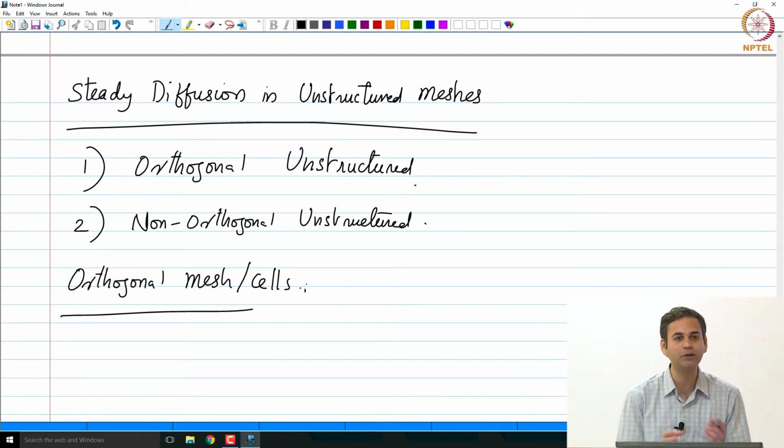So this was not happening because we have an area vector of the face in the same direction as the gradient, right? So the gradient direction is partial phi partial x, right? That is connecting what? That is connecting the cell centroids. So the line joining the cell centroids, if it is parallel to the area vector, that is an orthogonal cell, and if every cell in the mesh that you have generated satisfies this property, then what you have got is an orthogonal mesh, right.